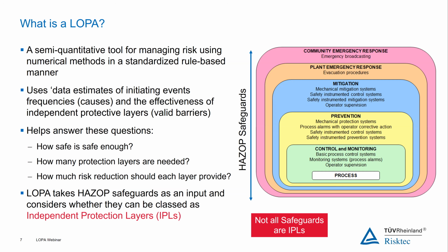The initial stage is really going to be looking at all the different types of SIL assessments and considering which one of these is the most appropriate for this operation, given the nature of the operations, the nature of your organization, the level of the risks that are being considered, and understanding and keeping in mind that if we do actually go simpler in how we apply our methodology and which methodology we choose, we will end up with a more conservative answer, which will inherently put more stringent requirements on us at the back end and the output of the assessment, requiring us to define a higher SIL level to the safeguards that we may have in place.